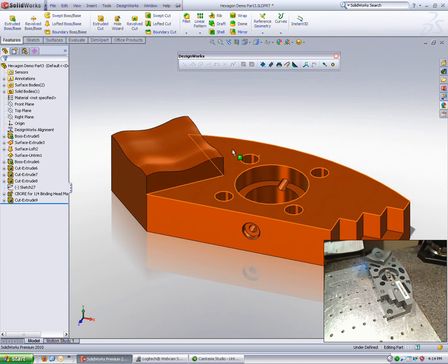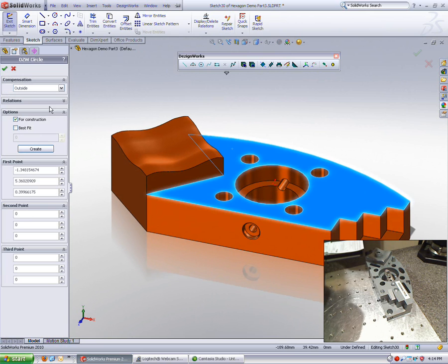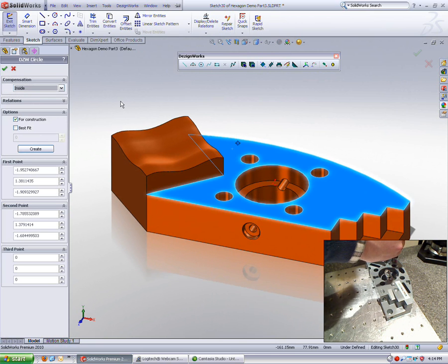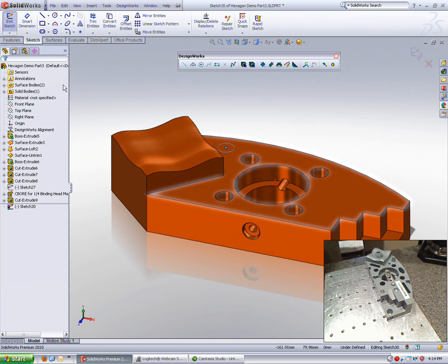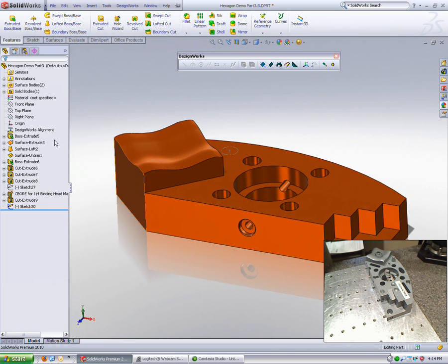Now, just like the lock surface where we're able to capture a cross-section of information, here we're going to do a lock plane. We're going to use it in a way that is a bit unique to this type of application. First, we're going to get a location for the cone that's sticking up off the top of the surface, again using construction, because we're just going to use the location of the center point of that circle. And we're going to offset a plane up to that center point, and that plane is going to become our lock plane that we're going to take a cross-section through.